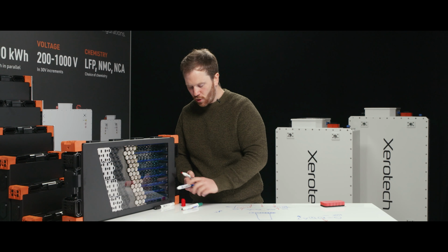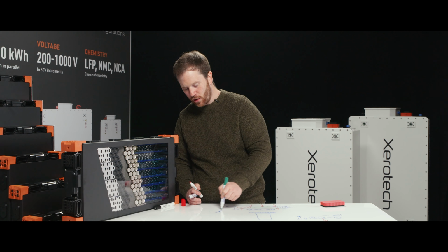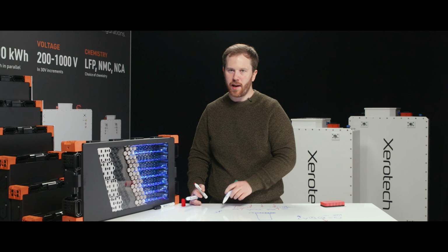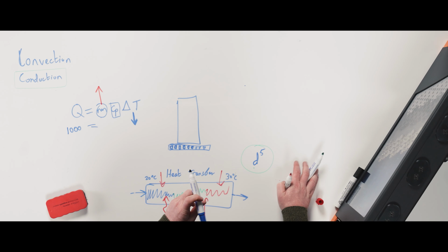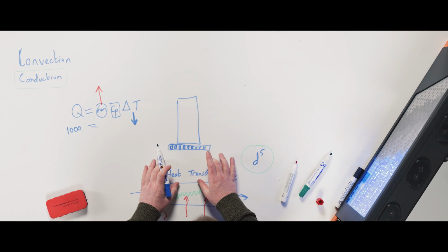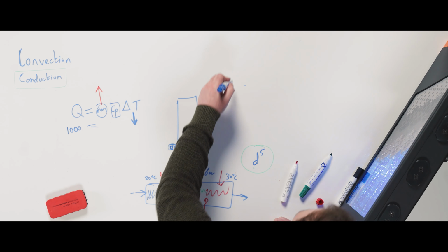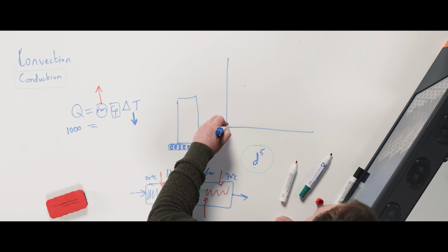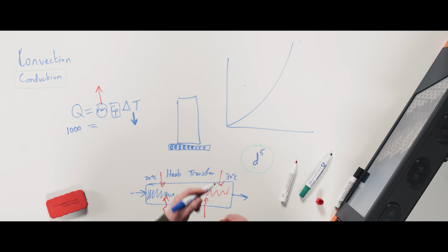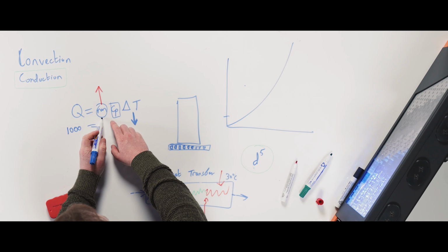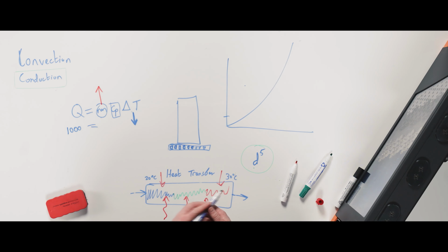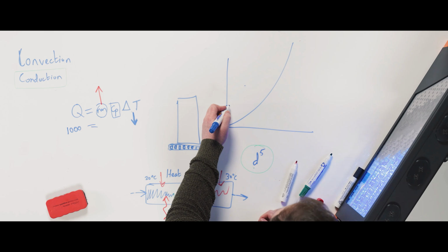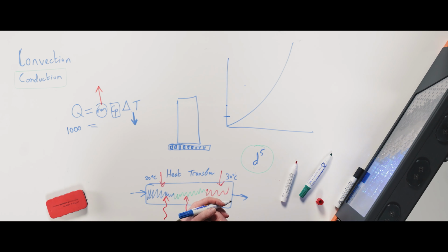So remember the equation I wrote down, this Darcy-Weisbach equation. One of the key terms in that is to the power of 5. And what it actually ends up meaning is that when we talk about pressure drop as a function of flow rate, it's an exponential. It goes crazy. So that means that, okay, I want to get my temperature gradient as low as possible in my battery, increase the flow rate, put on a bigger pump. The problem is that you're fighting an ocean, basically.